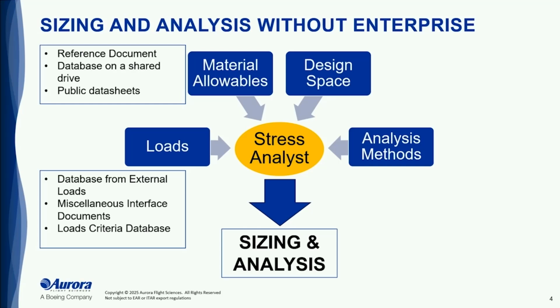When you're using novel materials, sometimes you don't have your full material allowable sets like you have from an OEM on your startup, and you're constantly injecting new data as you go through. So whether it's a reference document, shared drives that you're pulling from, or public data sheets that are available, you have to really manage where that comes from. And as a stress analyst, that can become dangerous or at least cumbersome.